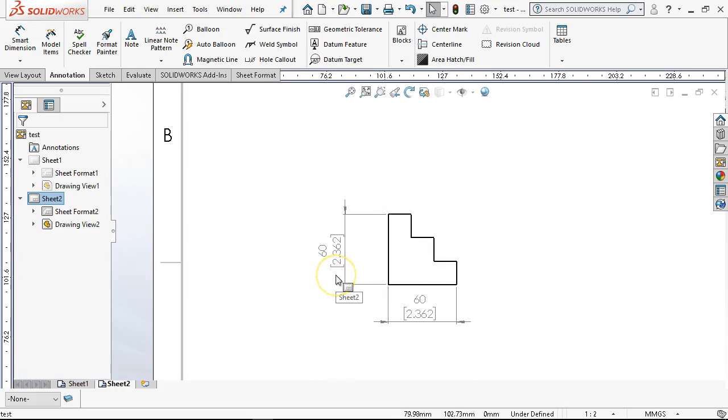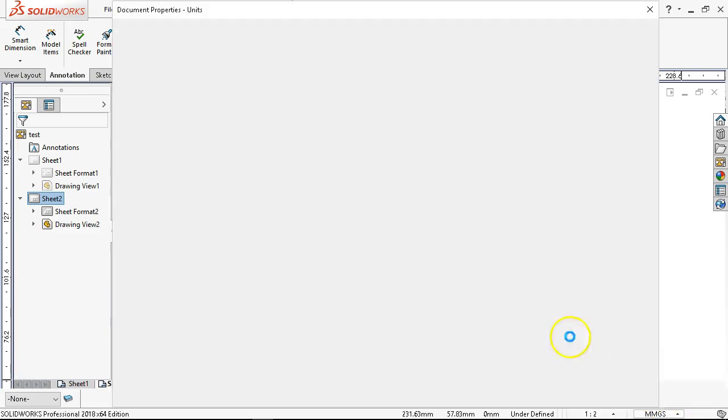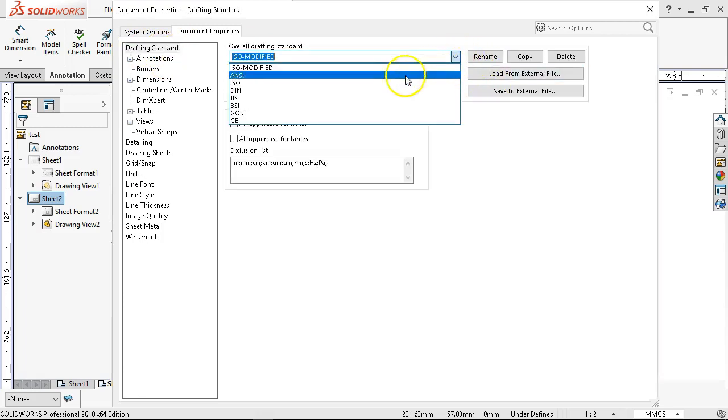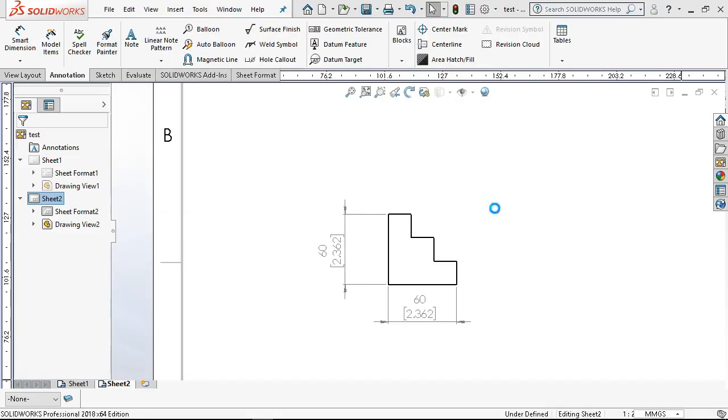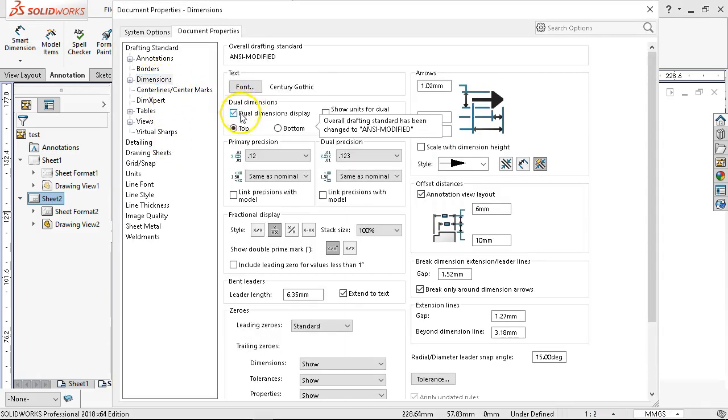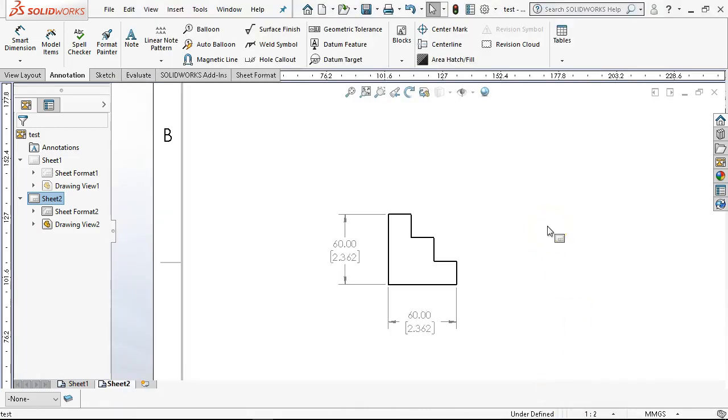And then now I'm going to get the bracketed number that tells me top is millimeters, bottom is in inches. Or I can put them off to the right side, to the left side, however you want to organize it. And then keep in mind too that this is the ISO drafting standard. And like I said, I started using it and decided it had some advantages. But if you prefer ANSI, switch it over to ANSI. Oh, and did it get kicked out? That's interesting. I didn't know I'd do that. Dual dimensions on bottom.